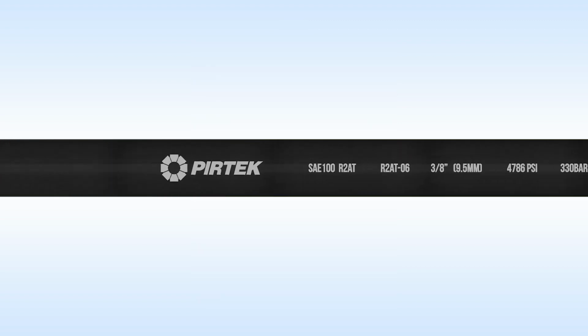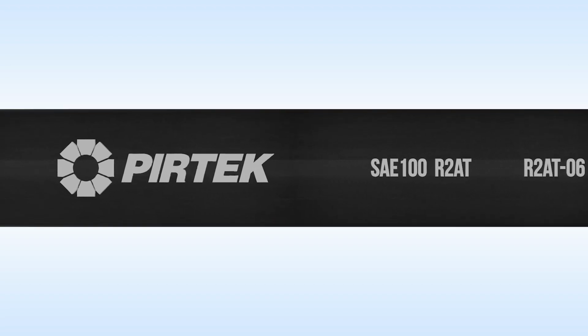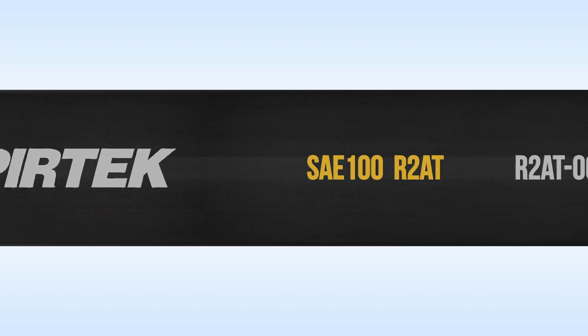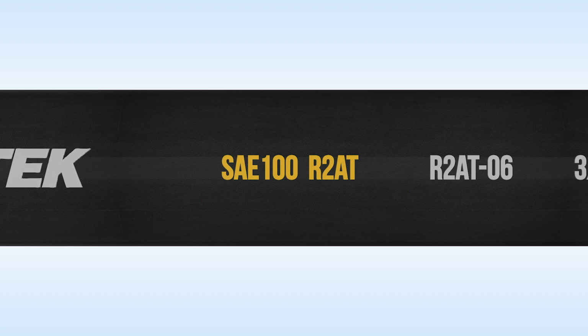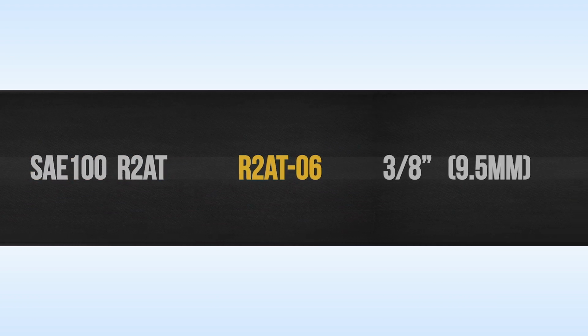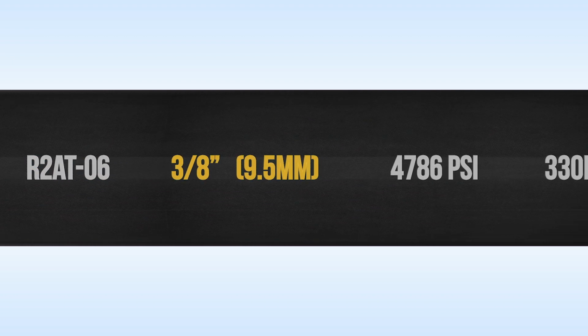Looking at the image of this lay line, does anyone know when the hose was manufactured? The lay line indicates that this is a Pertec hose. SAE 100 R2AT is the standard the hose was manufactured to. 06 refers to the bore size. The size is 3/8 of an inch.